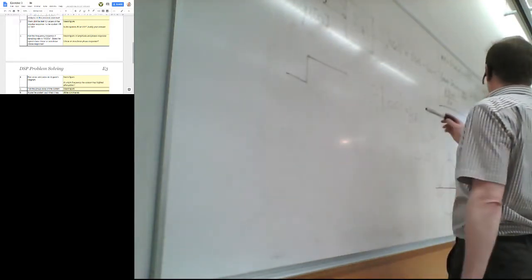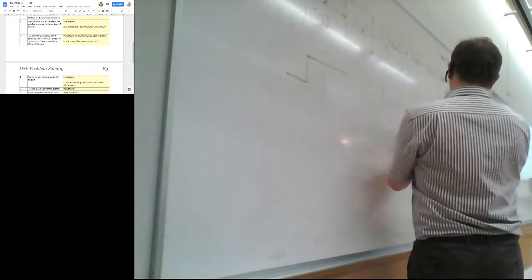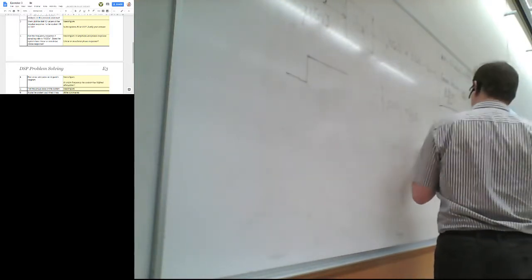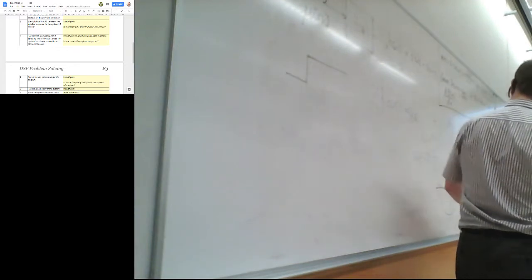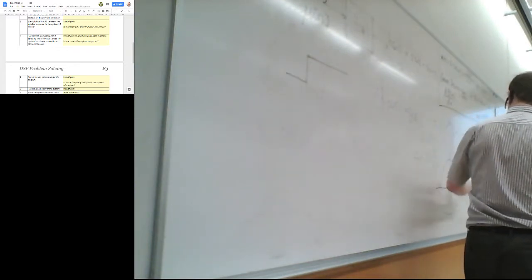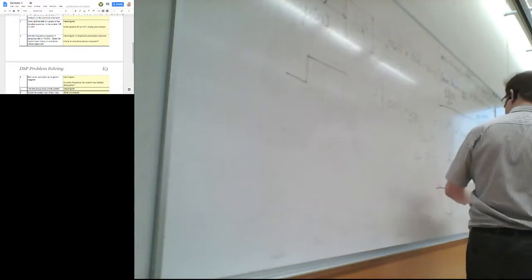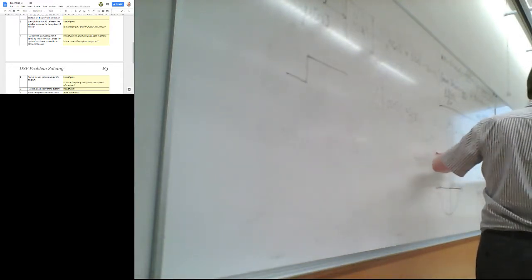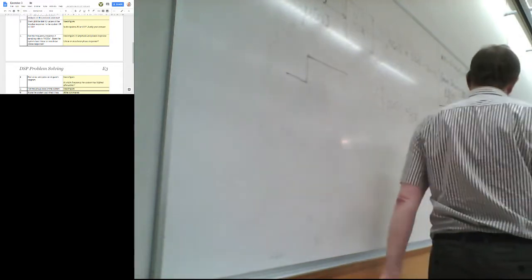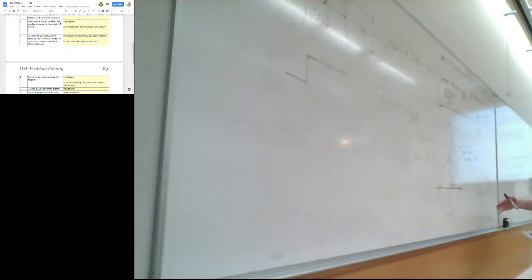Okay, there we have some responses. We have a frequency response, which is simply the transfer function evaluated at the unit circle, where this complex angle actually gives the physical frequency. It's directly proportional to the physical frequency. Then this one is a complex number, but for plotting, it's good to know the amplitude response, meaning whether this is low pass or high pass, and how much stopband attenuation it has.